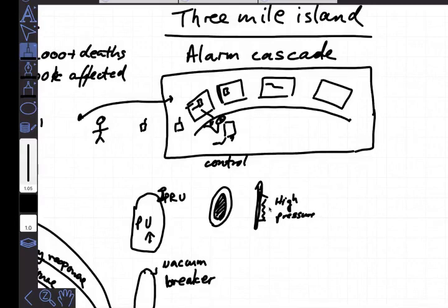Now, what is the problem with alarm cascade? I'm sitting here, and a little alarm pops up on one of my screens. I have to touch a button or click on that notification to make it go away. It's a little bit like when everybody joins at the beginning of these Google Meet meetings. There are 100 alarms at the same time. When we put these alarms in, it's unrealistic for somebody to take action on an alarm, other than just dismissing it, at a rate of more than about one every 7 minutes.